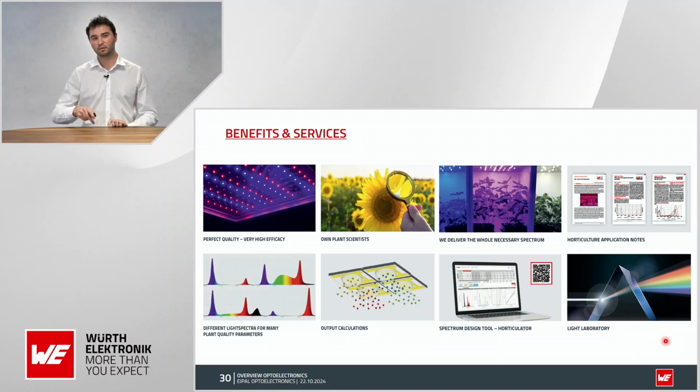They use specific wavelengths for specific processes. So when you look at horticulture lighting, most of it looks like this, a mixture of red LEDs and some blue LEDs, and maybe a certain type of white. With this, you can make the lighting much more efficient, because you give the plant only the color or wavelength that it really needs for doing something.